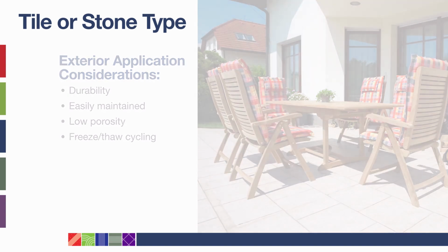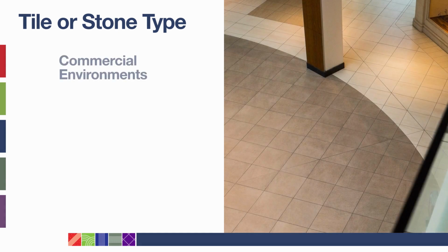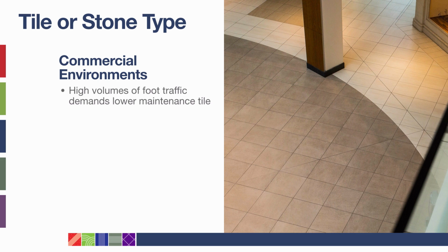Using large format tile in commercial environments can provide considerable advantages over other types of tile. Commercial environments frequently experience high volumes of foot traffic. For that reason, lower maintenance tile are often specified for commercial interiors as well as exteriors. One way to reduce maintenance is to specify tile with lower porosity.